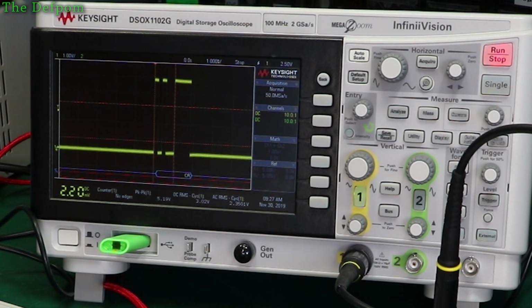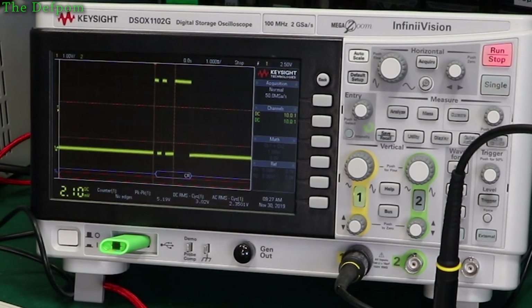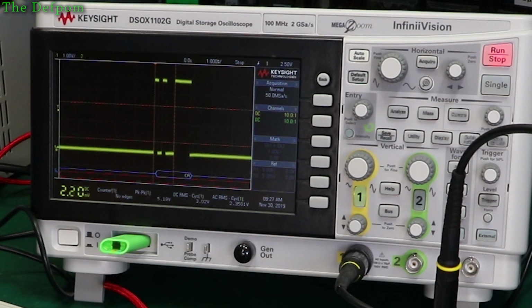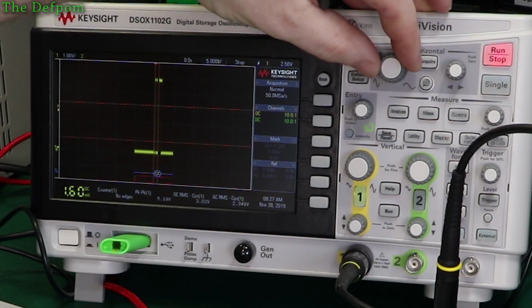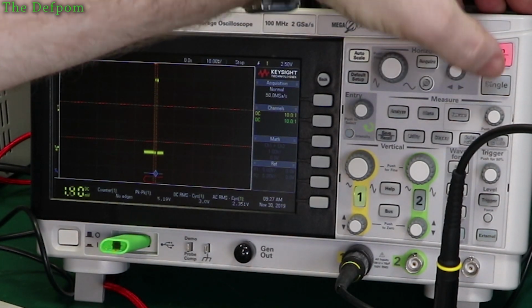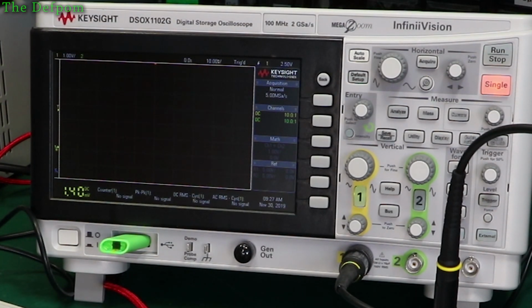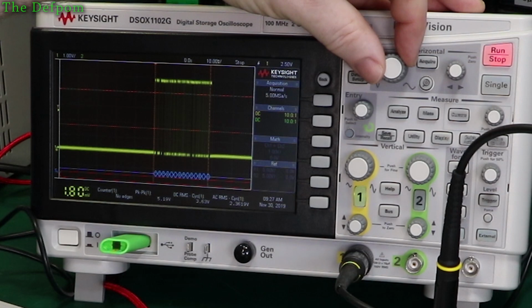You have to go into decimal decoding and get the decimal numbers out of that instead, or binary, or maybe hex, whatever. But as we're doing a UART and it's basically text coming through, then you know that it's a carriage return. So that's the first pulse that comes out of it. I'm going to make this a bit narrower so we catch the next pulse, because it's much bigger. Do a single capture and we'll stop it. That's what it does when it stops.